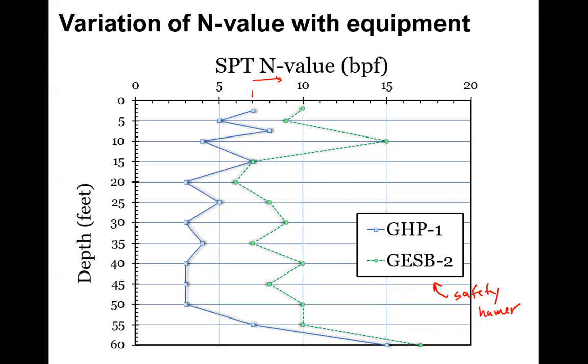So what this is doing is telling us a false flag. We are thinking that the soil is stronger than it actually is just because the driller got tired after a long day of working.